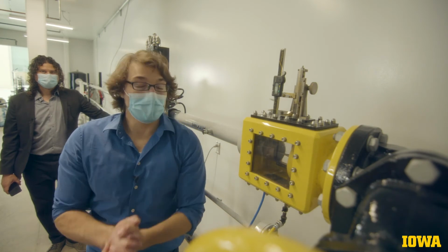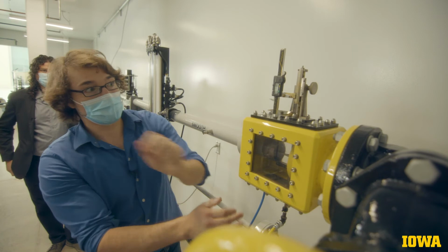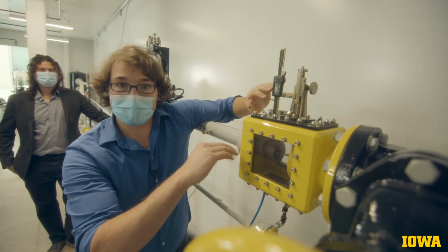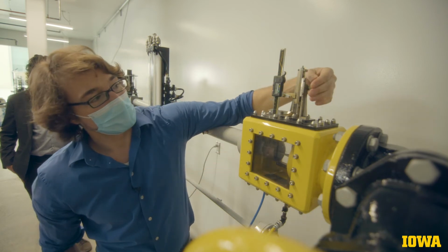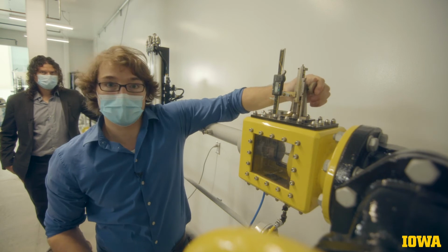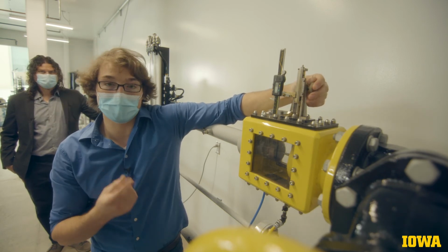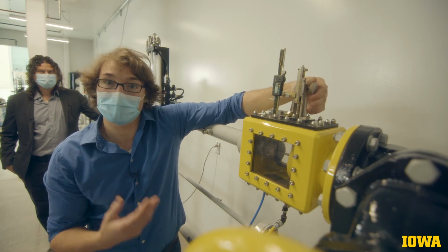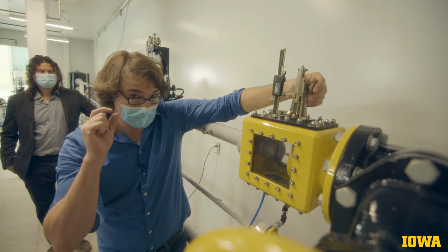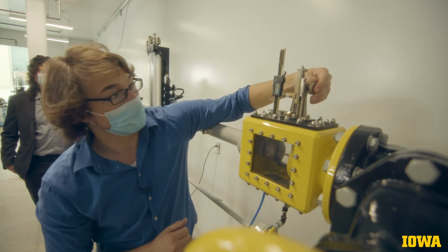Okay, now we're going to be measuring the velocity profile across the pipe using our pitot probe. We have our calipers zeroed with the stagnation probe along the center line of the pipe. So moving it down, we'll get negative values from center line, and moving it up, we'll get positive values. We're going to be measuring at radial distances from the center line of 0, 5, 10, 15, 20, 23, and 24 millimeters, which will take us just up to the edge of the interior surface of the pipe.